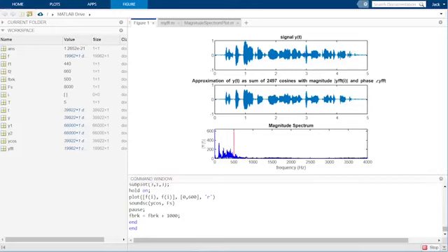Okay, so when we run it, we pause after 500 hertz have been included, which amounts to 2,497 cosines. We heard the muffled sounding version of the audio signal. That muffled quality is what results when we remove all frequencies higher than 500 hertz, and only keep frequencies lower than 500 hertz in our signal.